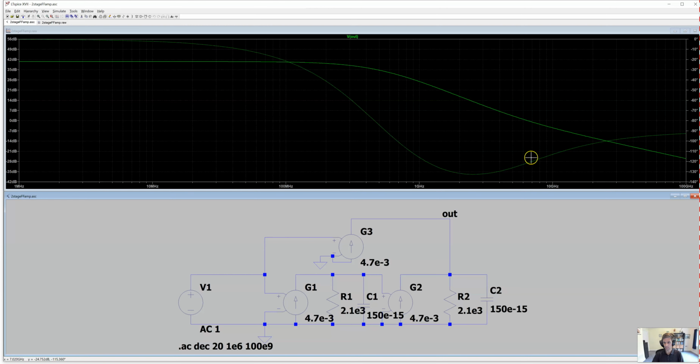There's some slight deviation from that because the zero, in addition to changing the phase response, also introduces a little bend in the magnitude response, so it extends the unity gain frequency a little higher than our calculations assumed, but the approximations are all pretty good here.